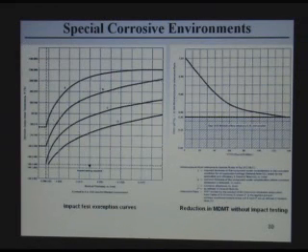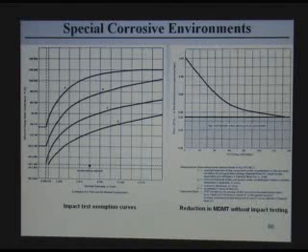This is from the code UCS 66, which shows each line as a group of materials. This is, for example, structural steels. This one is carbon steel, killed carbon steel, but not normalized. This one is for carbon steel, killed steel.